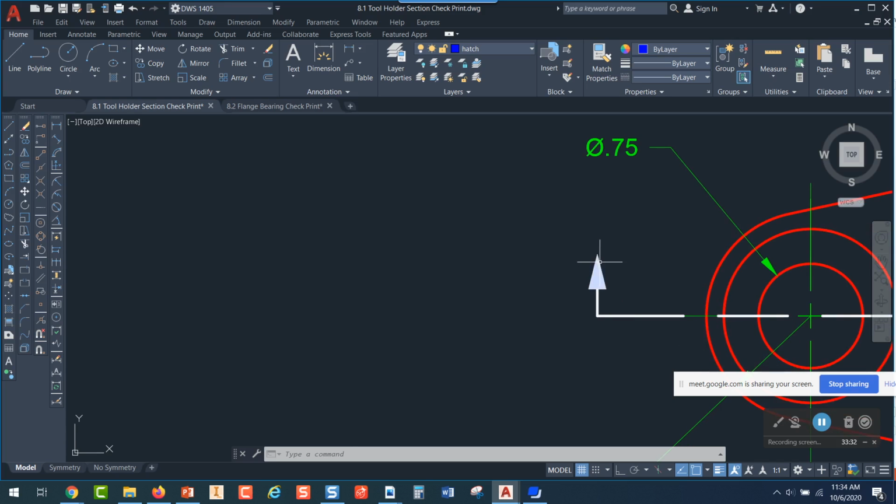When I draw this arrowhead right here, I actually draw it using a Polyline, and I mentioned the Polyline a minute ago. The Polyline command is right over here, under the Draw toolbar. You can also get it right here, Polyline. When you pick on Polyline, one of the things it will let you do is give it a width.